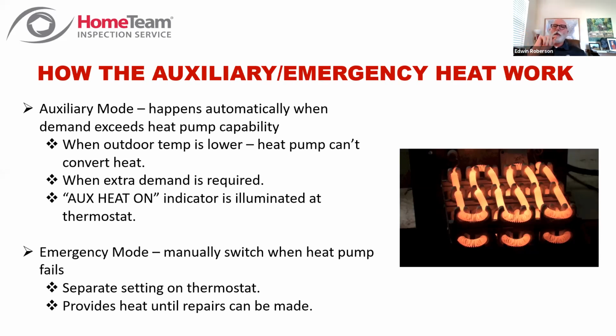Well, if you came in and you bumped it from 65 to 66, and when it caught up and shut off, and then you bumped it to 67 and it caught up and shut off, if you went 1 degree at a time like that, the heat strips wouldn't kick on because the heat pump would, to the extent that it could, do the job. But when you come in and give it that 7 degree differential, you're telling that system, give it to me and give it to me now. And so what it's doing is it'll kick in those heat strips.